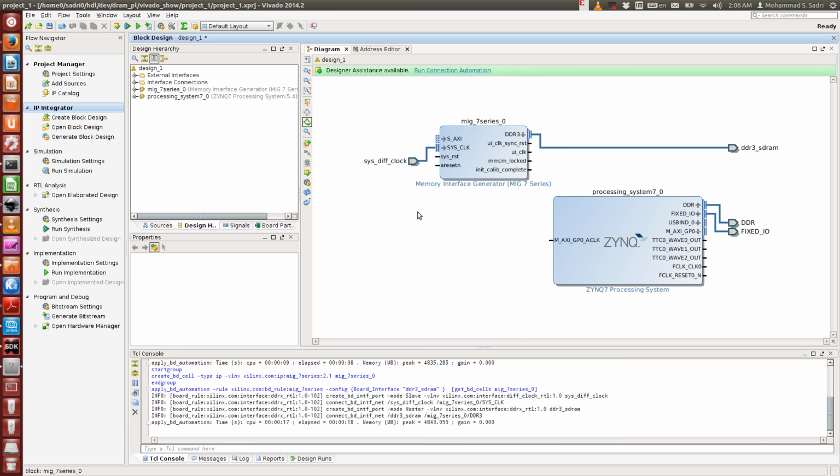It will go to 400, and as far as I know, this 400 clock will be used by the PHY. So if this is the case, and if the PHY is using a 400 megahertz clock, then the maximum rate that I see is 800 mega transfers per second, not more. So I don't know. This one I don't know. Okay, anyway, we have this guy here,